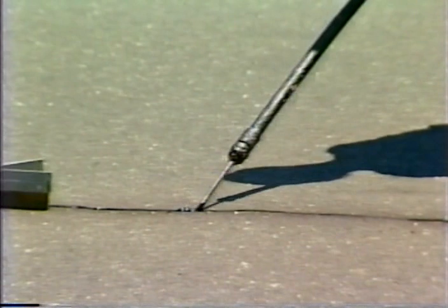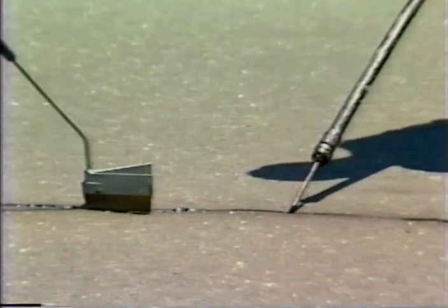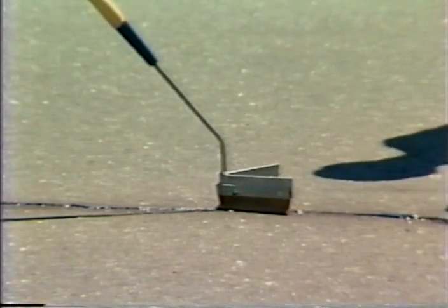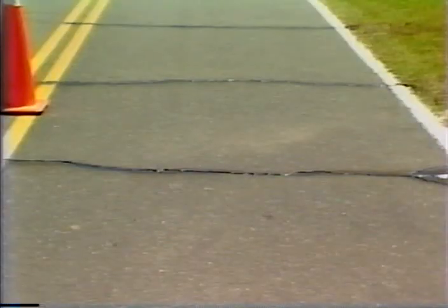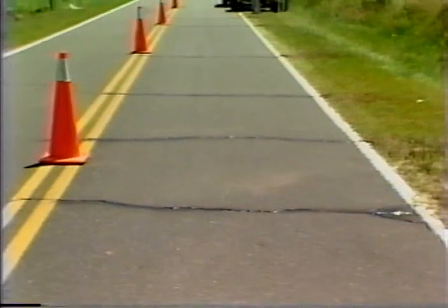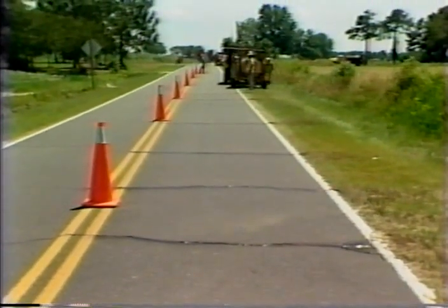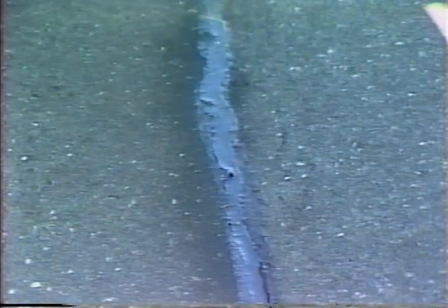This is necessary because the sealant material cools quickly and is difficult to squeegee once it cools. Rubberized asphalt sealants do not require any blotting material after application. Once the sealant has cooled, the road is ready to be open to traffic. The time required is approximately 15 minutes.